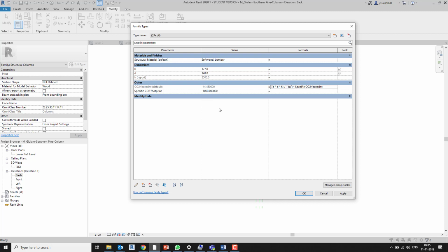I can do some calculations by hand and check. I think it's a good idea at this stage. You should never trust Revit. Do some calculations by hand, because I don't know if you notice here, but on top where I have my mouse, we are talking about millimeters, right? Millimeters times millimeters times millimeters should give me cubic millimeters, but Revit somehow gives me cubic meters. So be aware of that. I know that this value is correct because I tested it, so it's fine.